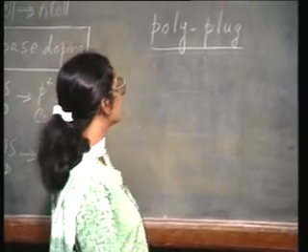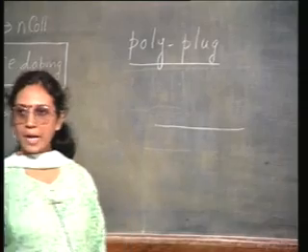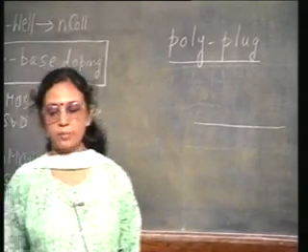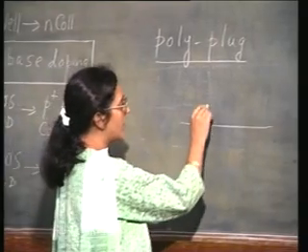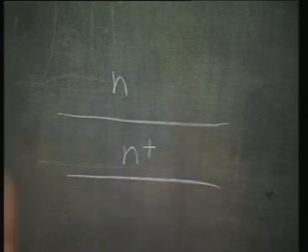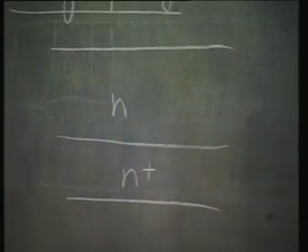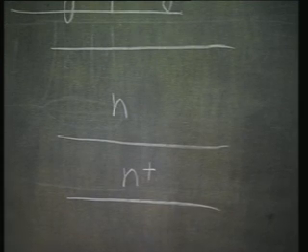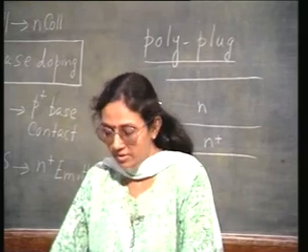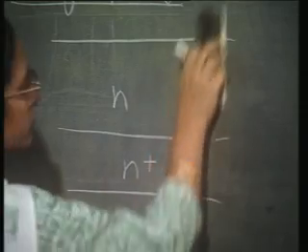So, you see essentially what you have here is, I am just expanding the bottom of the N-well, okay. So, what you have is the N-well and the underlying N plus buried layer. This N-well is going to house the NPN transistor as well as the PMOS device. Okay. Now, we do an etching.